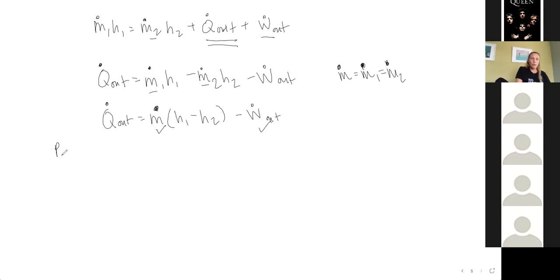So at point 1, our pressure and our temperature are equal to 1.6 megapascal and 350 degrees Celsius, respectively. I think this is going to be a superheated vapor because it called it steam and it called it saturated vapor at another point. But we can check that in our tables.